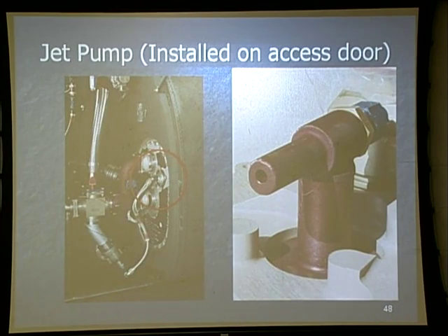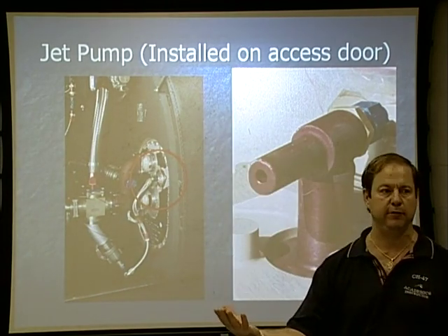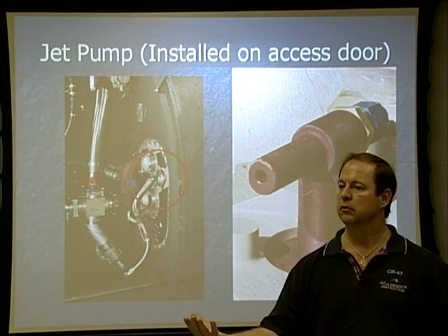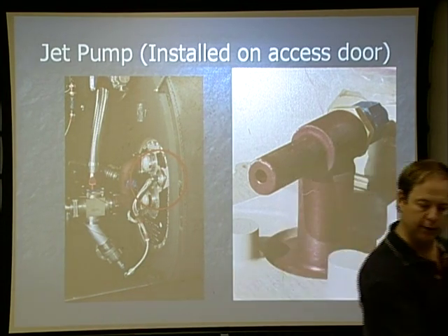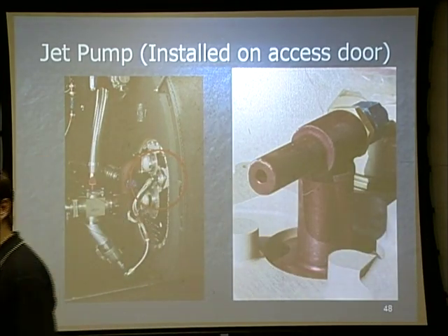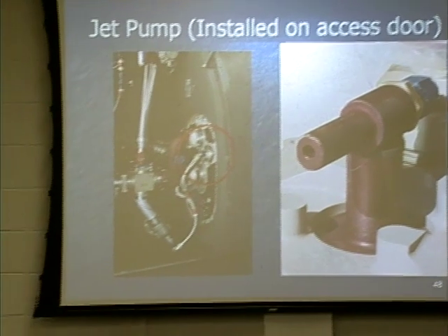Now, our jet pump. We talked about a line that allows fuel during the refueling process to transfer from the right side of the fuselage, right side of the aircraft, over to the left side. We said there was a line that runs directly underneath between those two forward intertank areas. Agreed? Does everybody remember that on that first picture? The D1 receptacle is attached to it. It allows us to refuel all 6 tanks simultaneously.